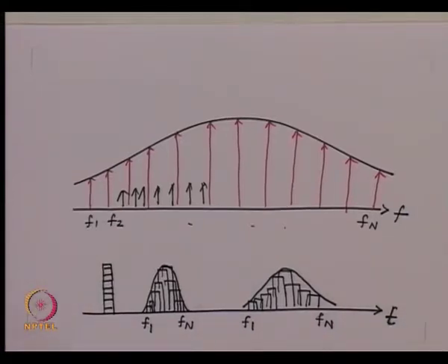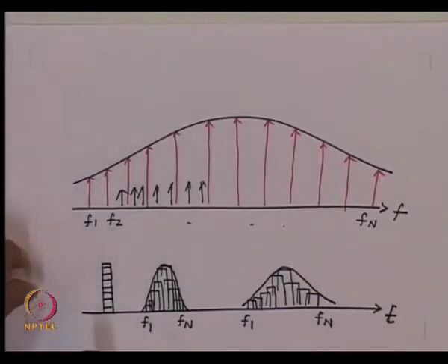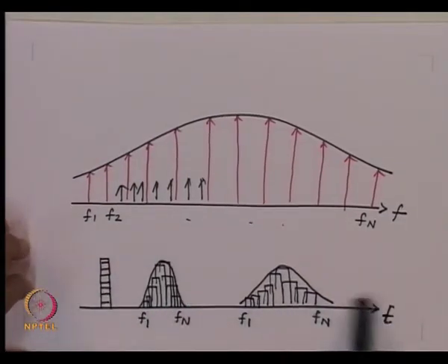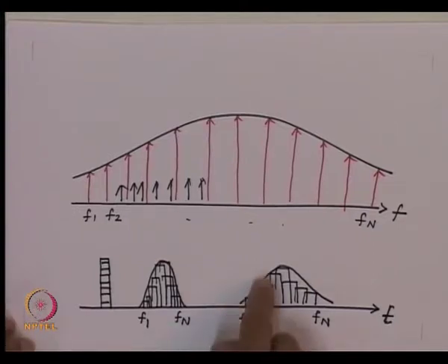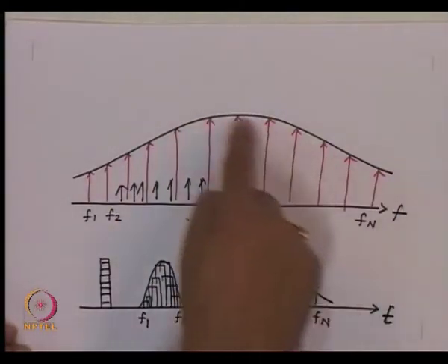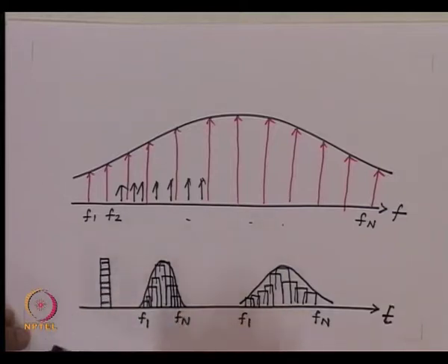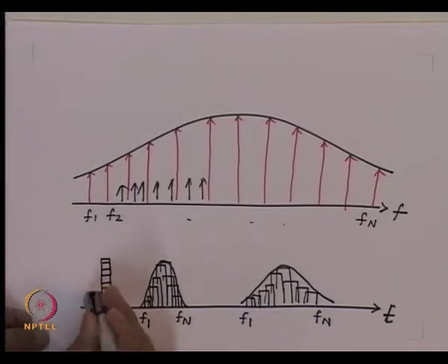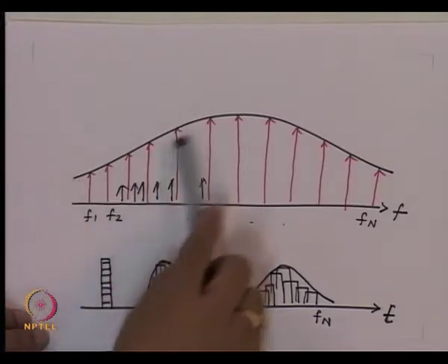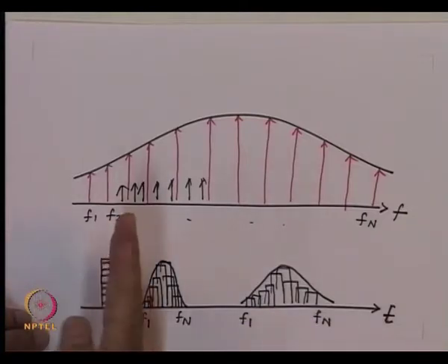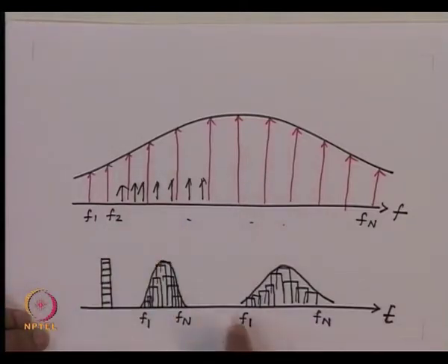So as we argued earlier, as these pulses travel more and more on the fiber, the pulse gets more and more broadened. One can ask, what is the shape of this function? In fact, the shape of the function is decided by this profile. Because initially the spectrum was like this, perpendicular to the plane, and as they travel, this function slowly tilts like this. So the projection of this function taken on time, because of these differential velocities, will get reflected into this profile.